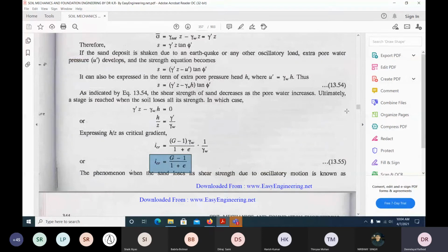After that, we saw the vane shear test. What is done in the vane shear test? We are applying a torque. We are rotating it by using the vanes. Then the vanes try to shear the soil, and by using laboratory equipment we can find out where the soil is sheared. The input is the torque that we are applying. Once you know the torque, and the diameter and height of these vanes, we can easily find out the shear strength S.